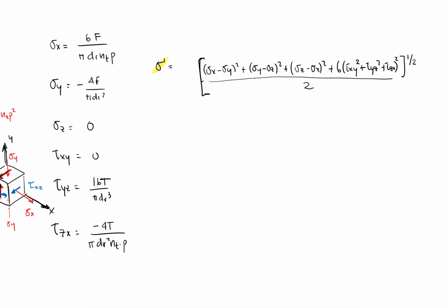Probably it's more static loading, so you would compare it to the yield strength. You don't want the threads of your screw to deform permanently, or for that matter the ones in the bolt, but they should kind of match. It's not the exact same number, but the process is pretty similar.